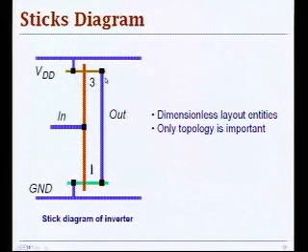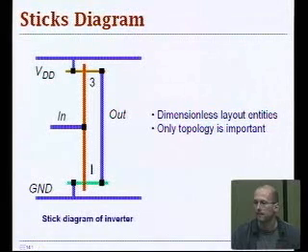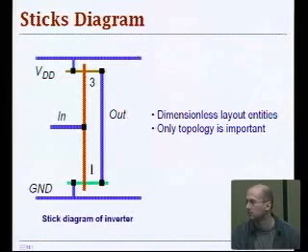So you have, for example, horizontal diffusion for the PMOS, horizontal diffusion for the NMOS, give it a relative size with these numbers here, and define the connections. And then there is a bunch of tools that can automatically take this sticks diagram, and also know the design rules, and can provide compaction, translating this into your real layout.